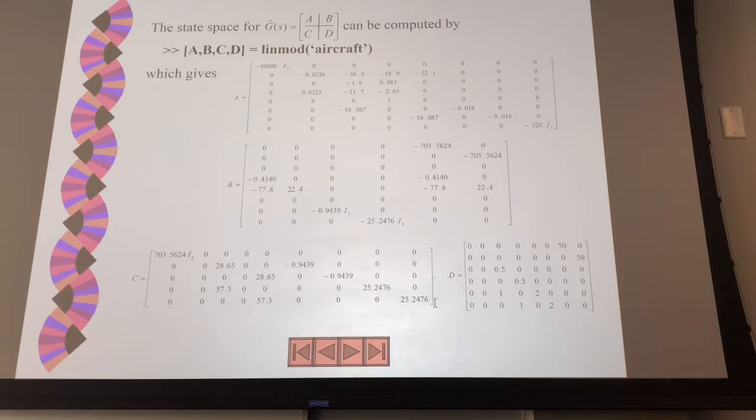So the aircraft model could be very nonlinear. So you say, oh, I want to do linearization at an operating point to get an LTI system. Don't worry. If you do a linear model, they will extract the Simulink model and linearize it for you automatically. So go and understand the linmod command, and they will give you all these A, B, C, D from the Simulink model.